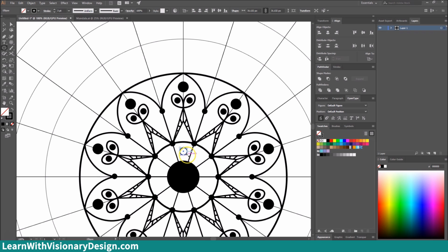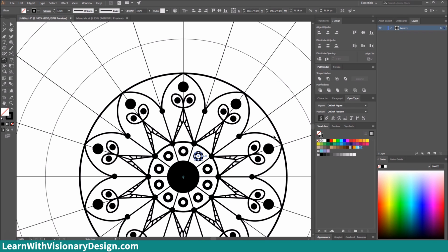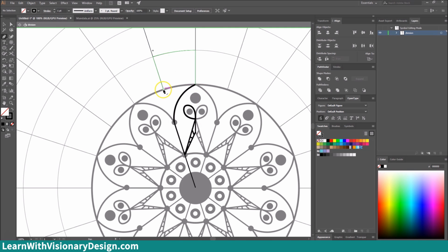As I stated earlier, from this point on, all steps are similar. I'm just following my inspiration and creating. You can design it the way you like. You can follow along to see the steps I'm doing. Sometimes something similar to this happens where clicking the pen tool to create a line gets connected to an anchor point near it. If you don't want this to happen, lock the line that is constantly being connected by pressing Ctrl and number 2 on your keyboard.